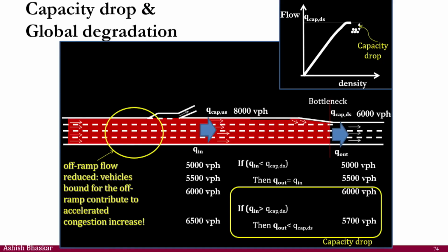Yeah, because side friction is going to create that, but it depends on what level of modeling you are doing. There are different levels of modeling. In microscopic modeling, you try to model individual cars on the road network. Mesoscopic modeling is the cell transmission model I mentioned, where you model the traffic as flow from one section to another. And macroscopic is the simplest form of modeling. Between micro and macro, it depends on the problem at hand.